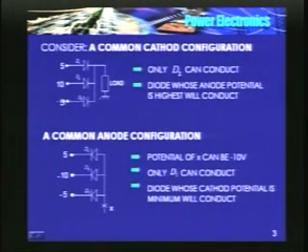There is plus 5 volts, plus 10, minus 5. We know that we cannot have a situation wherein a positive voltage appears across the diode. The moment the voltage across it is 0.7, it conducts. Assume that D1 conducts. If D1 conducts, cathode potential becomes 4.3, and if I consider it to be ideal, it becomes 5. Then what happens to D2?